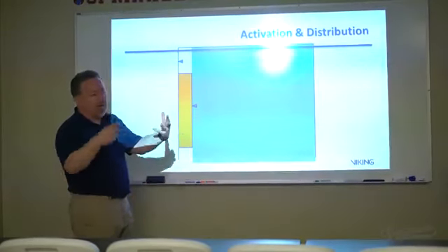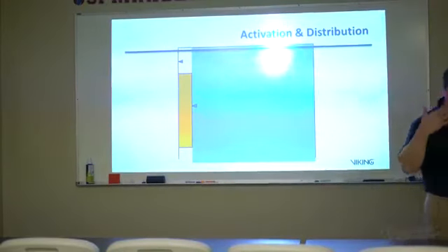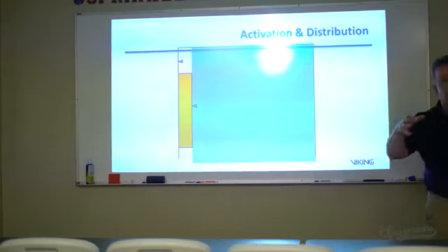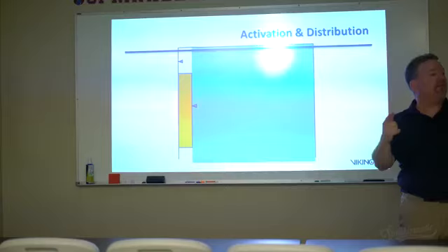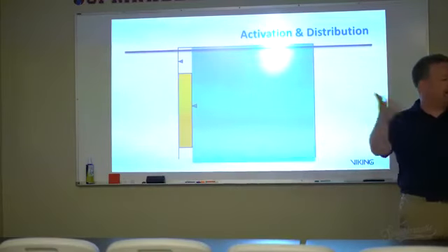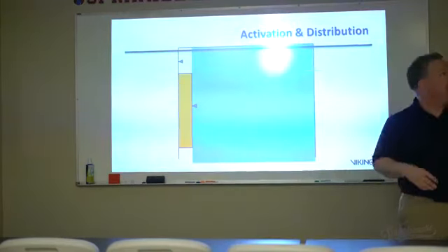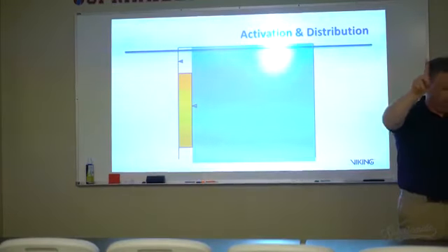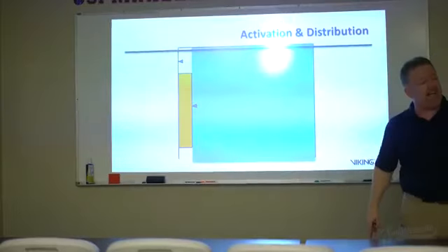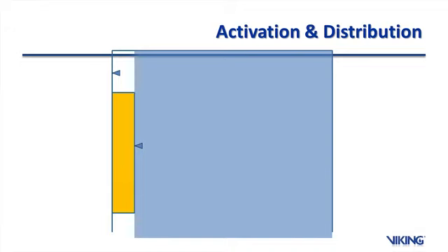of odd. Now, other times we're going to look at obstruction rules, and one of the obstructions we're going to look at is what if I've got a sprinkler in this room and I've got a pillar in this room. Can I protect this room with one sprinkler if I get the appropriate spacing? Let's just say maybe a 20 by 20 room. If this is just a 20 by 20 room, then I could theoretically put one sprinkler in here and protect the entire room. But what if I had a column in this room?